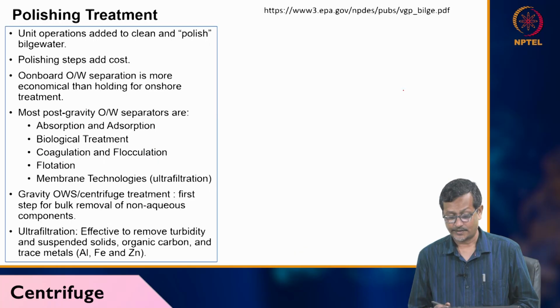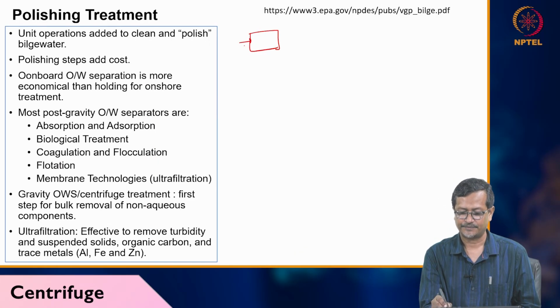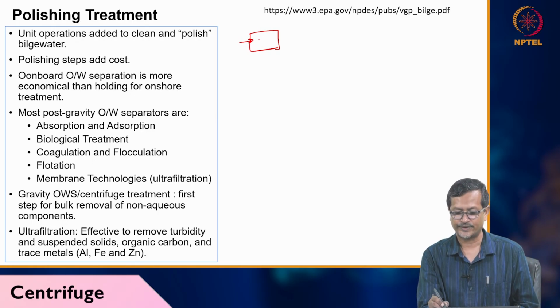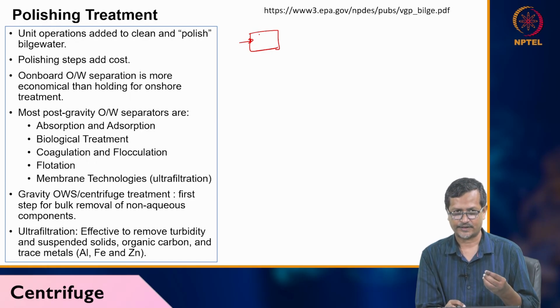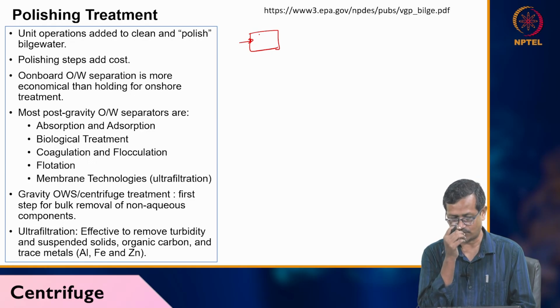Okay, now you got oil and you have a gravity settling chamber, because that will remove a larger amount of oil particles, but very small particles you are not removing, or if you have any emulsifying agent, then you cannot remove them using a gravity settling system. Gravity settling will work better if you have larger oil particles and no contaminants.